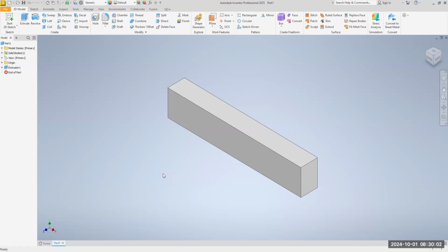All right, so we have the overall shape of the part. It's just a piece of bar stock. We're going to start making holes in this, kind of like what we did in the last assignment. However, this time we are going to create a section view, which is an imaginary cut through your part so that you can see the internal details. One more time, it's a full section view. So we're going to cut all the way across. I use the word cut loosely because we're not making a physical cut. We're doing an imaginary cut so that you can see the internal details.